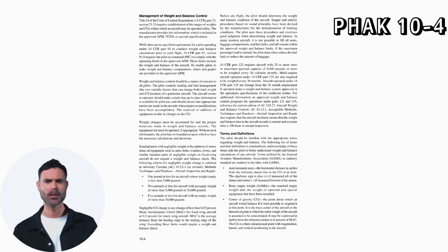To enable pilots to make weight and balance computations, charts and graphs are provided in the approved AFM. Weight and balance control should be a matter of concern to all pilots. The pilot controls loading and fuel management, the two variable factors that can change both total weight and CG location of a particular aircraft. The aircraft owner or operator should make certain that up-to-date information is available for pilot use, and should ensure that appropriate entries are made in the records when repairs or modifications have been accomplished.